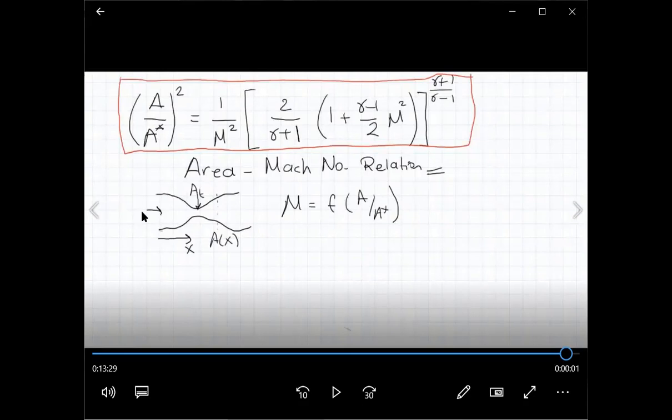So depending on the conditions inside the engine and depending on the flight conditions, the minimum area is changed to always keep the operation of the engine at maximum performance. The thing is, the flight control system knows how to change that geometry through usage of the area Mach number relation, which is already programmed into the flight controller and the engine controller of the aircraft.